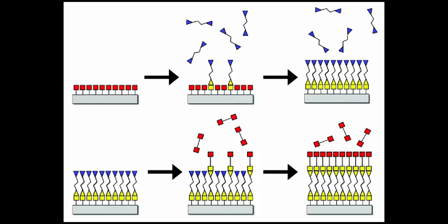Now I'm going to explain one of the processes used to deposit oxide films over a substrate. Metal oxides are difficult to deposit by thermal chemical vapor deposition techniques at moderate temperatures. Since ALD methods allow the separation of each reactant until they react at the substrate surface, more highly reactive species may be used and low process temperatures are also possible.